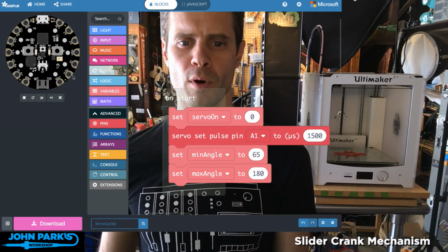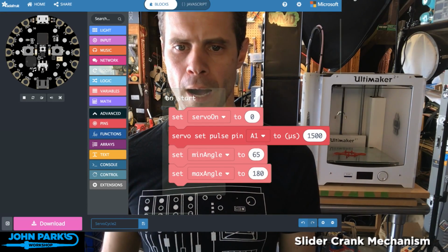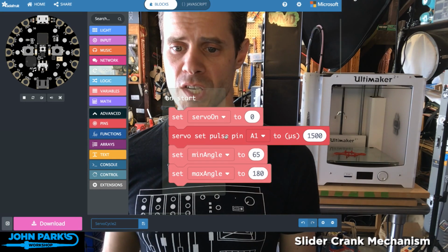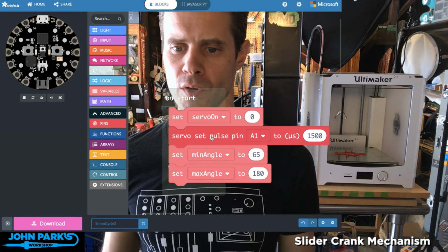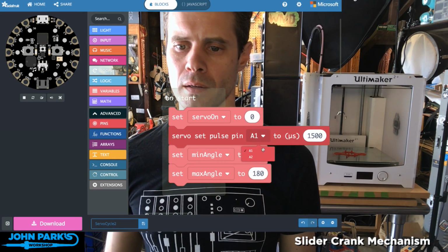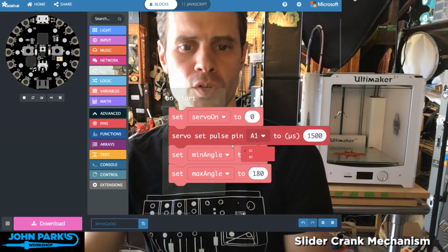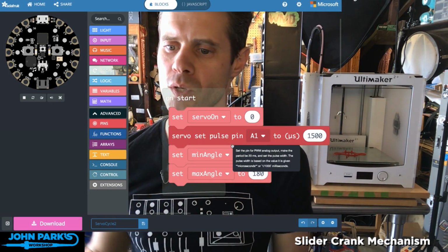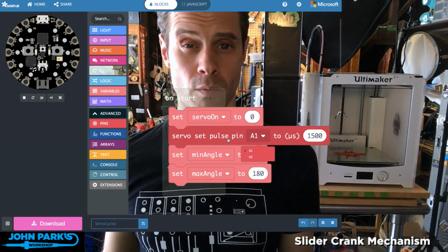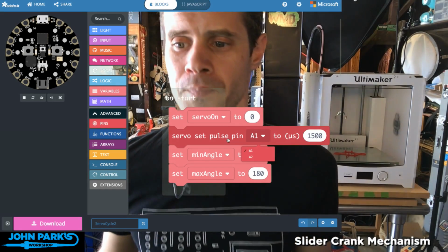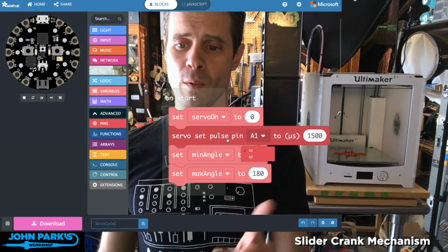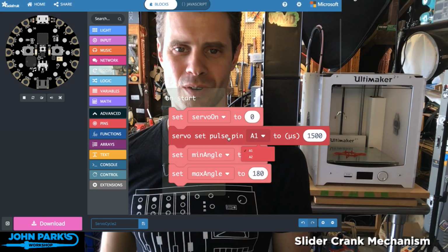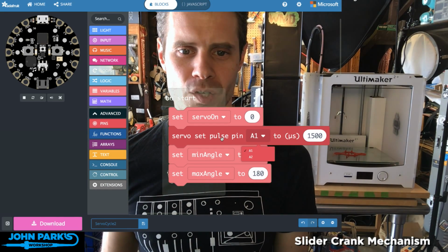Connected semi-permanently to the speaker and amplifier. But you can see here, when we're dealing with servos, we can talk to... oh, why is this one saying A1 and 2? Oh, are these the only pulse width ones? I could be crazy. Maybe we can only do 2 of them. Something that will be remedied with the Cricket, I might add. But, okay, take back what I said there. A1 and A2, those are the ones that we can send servo pulses out on, because those do PWM.